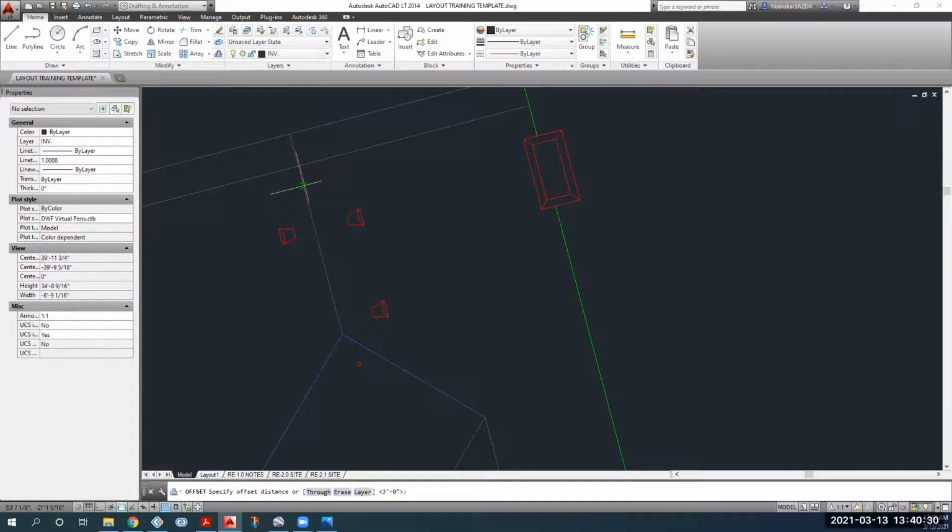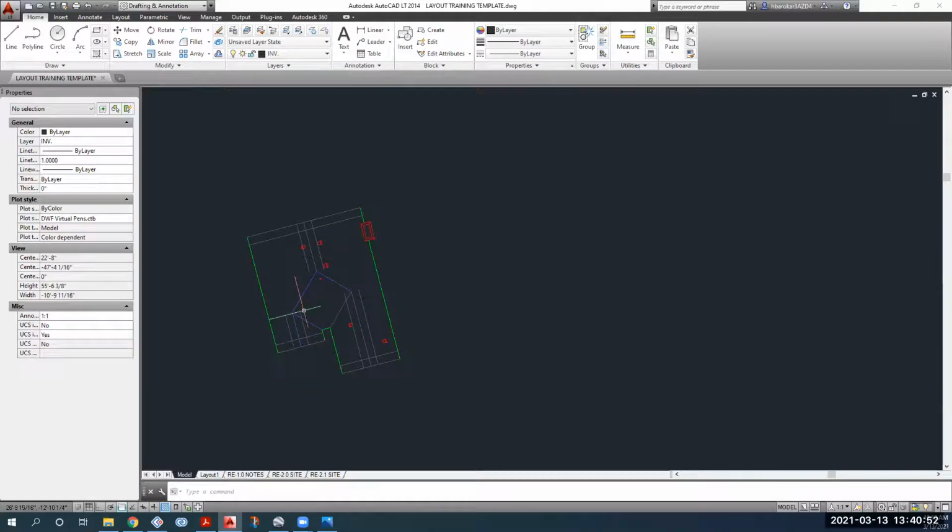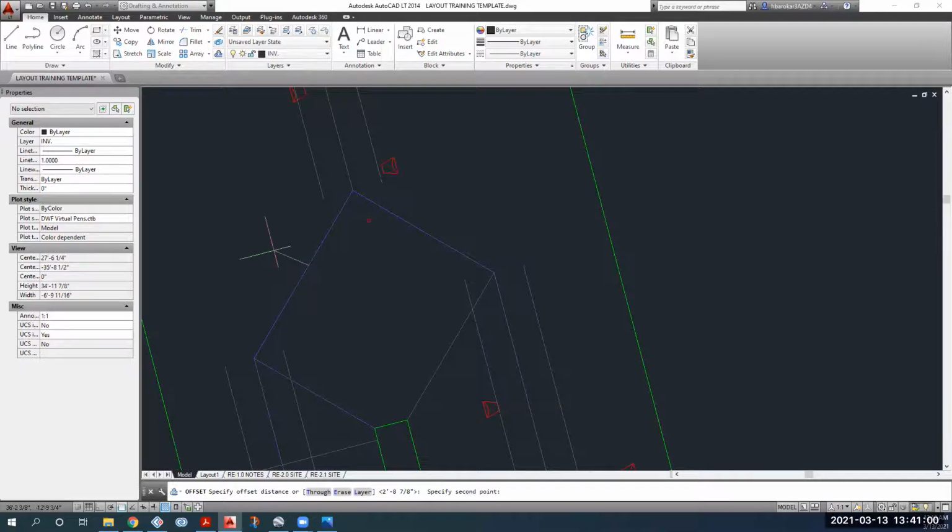So you again select the offset tool, go to the line, type in 32.888, press enter, and then offset it on the right, offset it on the left. Okay. Same with these two ridges. All right, and then to do the same thing with the valleys, now it is 18 inches, again unprojected. So go select them, go to 18 inches. Okay.